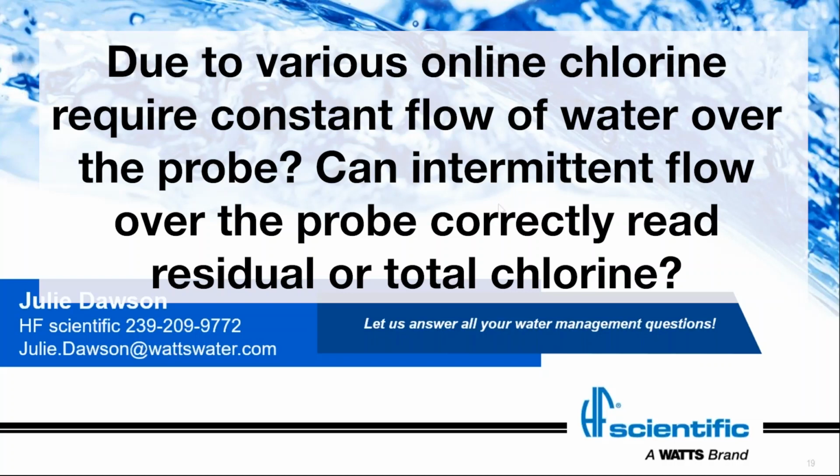For ion selective electrode, they do have an intermittent sample option where you can say, okay, I want to run this every 30 minutes. And generally that's done to save reagent cost. I don't know how well it would work with just on-off operation, but some manufacturers, including us, do have a standby option where you can actually send a signal to the analyzer and say, shut this analyzer down and bring this analyzer back on. But you can't do that with amperometric because that's not how it's designed. It does need a constant sample flow.